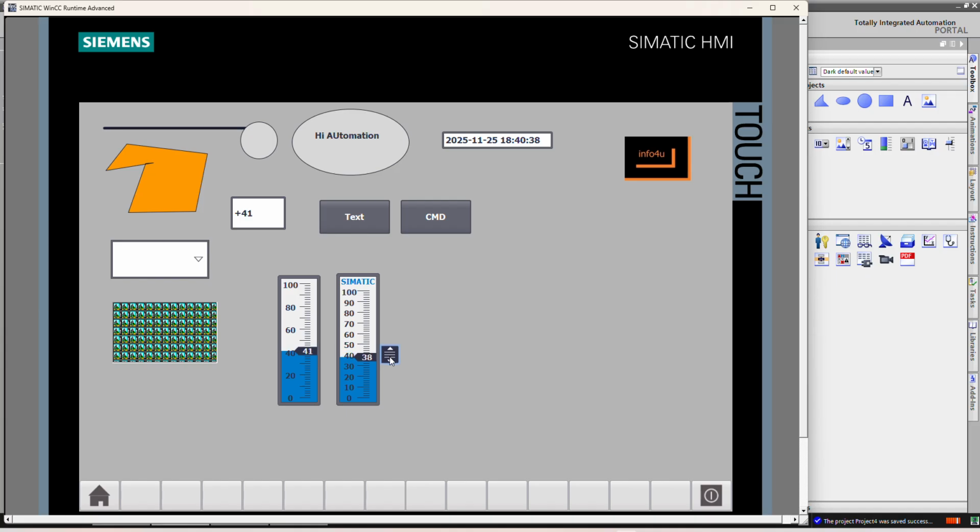So here you can see if it comes less than 4, then you can see in the combo box the value and the respective picture. So in this way we can use it to change the speed of the VFD or control valve opening or anything else, so that the operator has no need to enter the digits in the keyboard. It will be better, there will be fewer clicks on the HMI.